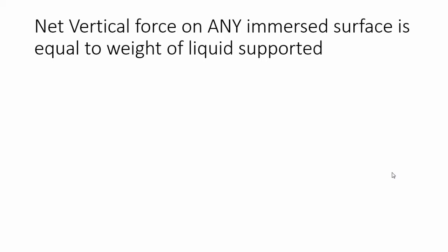Now, very simple. For any object or surface, the vertical force on any immersed surface is equal to the weight of the liquid supported. What do I mean by that? I have some region, and I want to find out how much is the vertical force supported by this piece. Okay, how much is the vertical force?